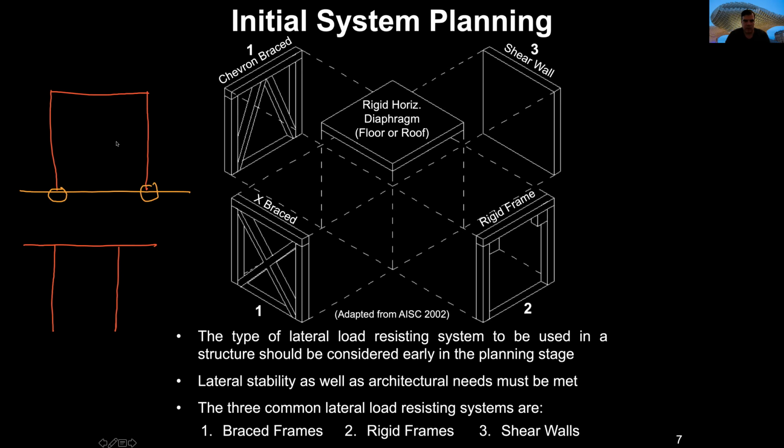However, when we speak about steel, those frames need to be rigid. If the frame is not rigid, as you already know, the frame will tend to move and do something like this. It will deform. For example, if we have a load on this side, as we can see, one of the sides will rotate.